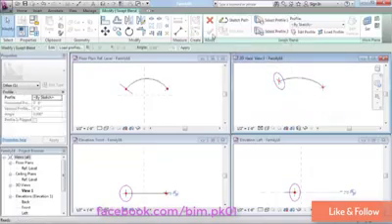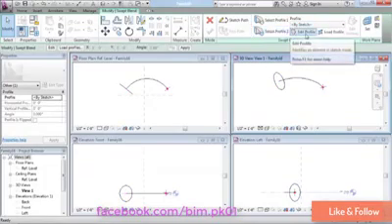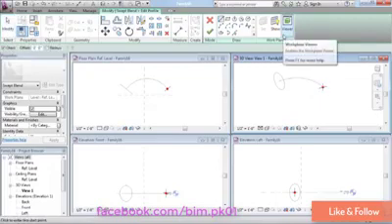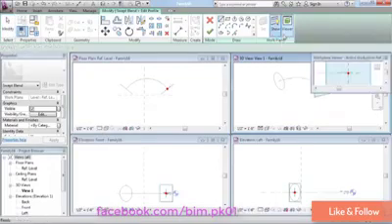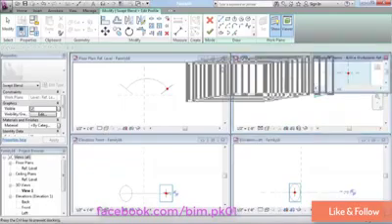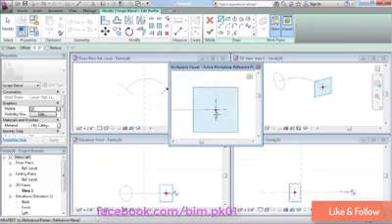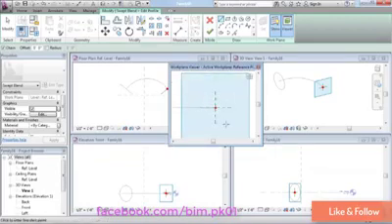Well, let me finish this and switch to the second profile. Okay, so I'm just going to click this button and do Edit Profile just to show you one alternative that we have here. If I click the Modify tool, if I click this Viewer button, it's called the Work Plane Viewer, you'll get this secondary window here. I'm going to move it out of the way. I'm going to make it a little larger so I can actually see what I'm doing. And now you can see that I'm looking right at that plane. If the angle of the plane is not conducive to giving you a proper sketch, then you can use this Work Plane Viewer feature and it should make it a little easier.